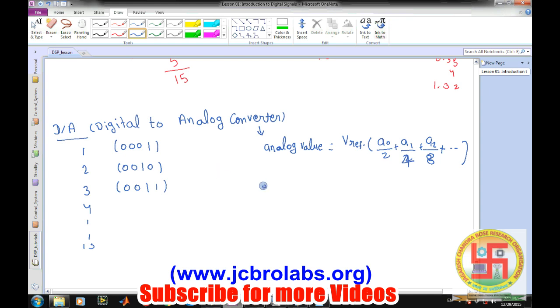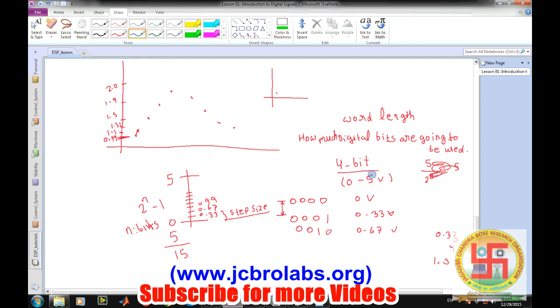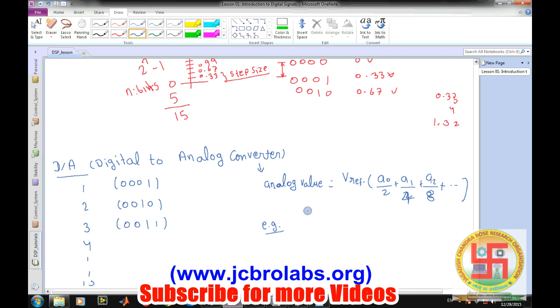So let's take our previous example. We used this 5 volt as a reference because this was the maximum value, and a 4-bit number. So our number was, let's say, 0010. The corresponding analog value will be V reference 5 into 0 by 2 plus 0 by 4 plus 1 by 8 plus 0.